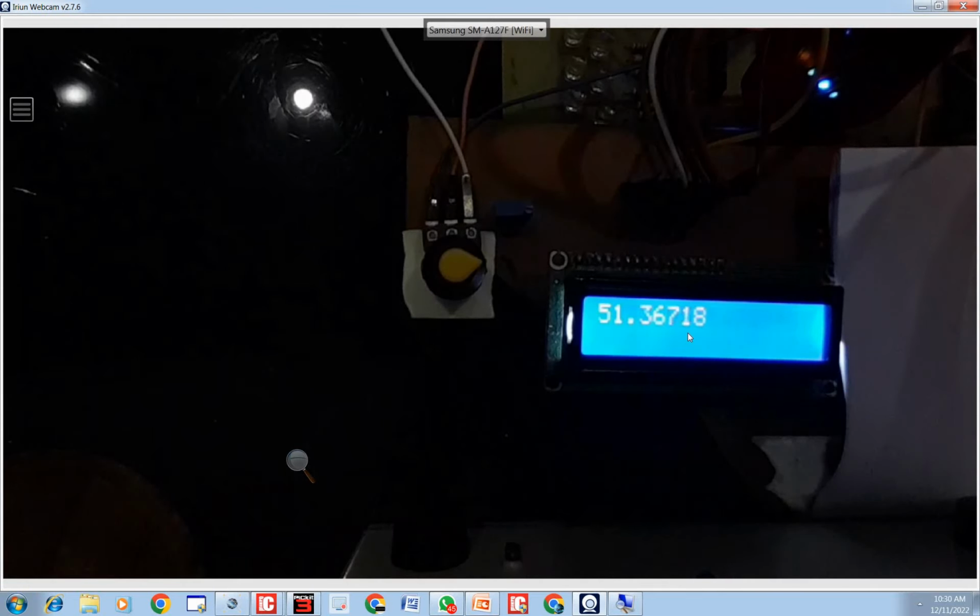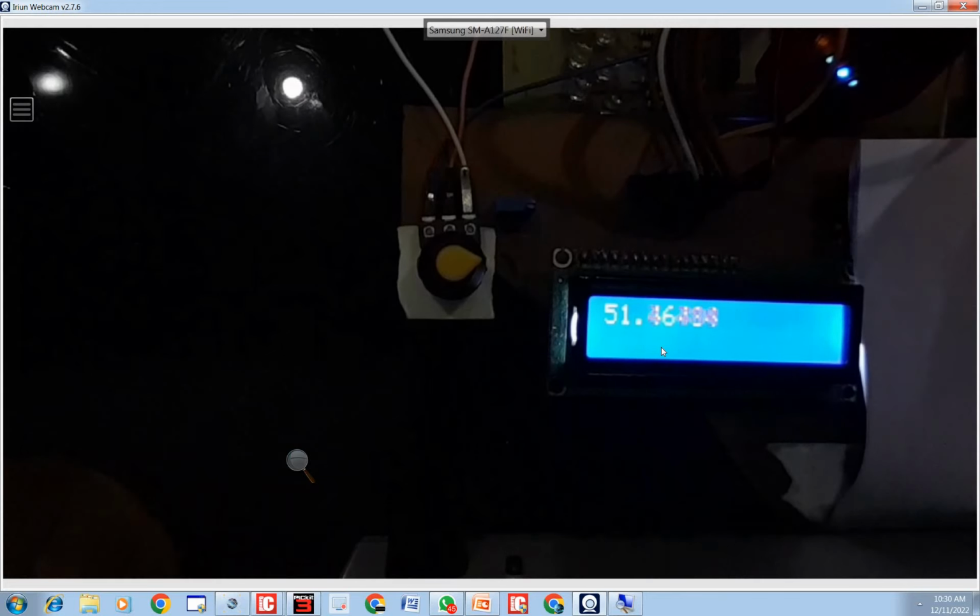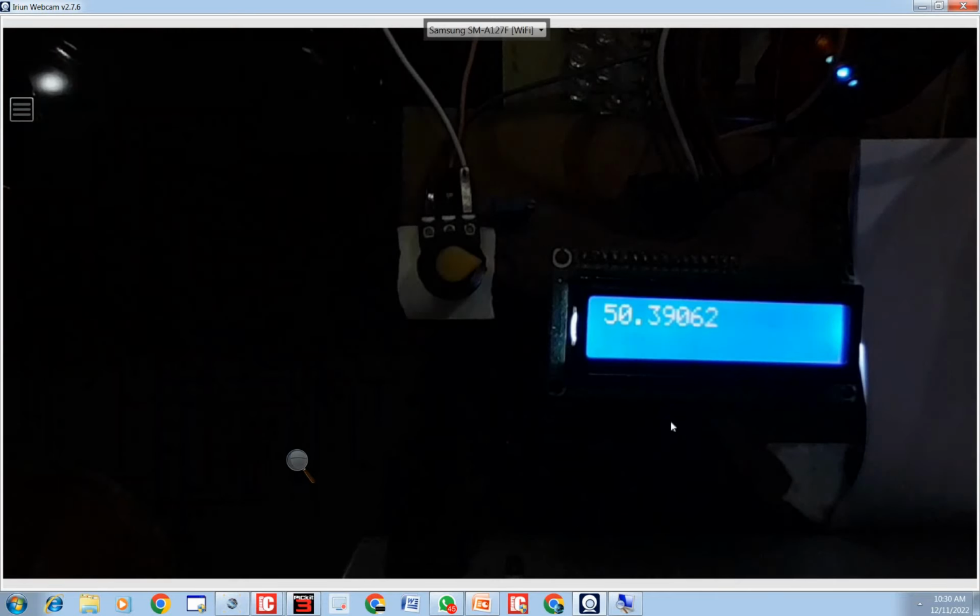Okay, as you can see, as in the presentation, it is doing exactly what we needed. Now let me move this potentiometer. Now it is no longer showing values from 0 to 1024. Now it has been converted into a percentage like this. See, the more I rotate, the higher it goes, and its accuracy depends upon the accuracy of this potentiometer. This potentiometer is this much accurate.